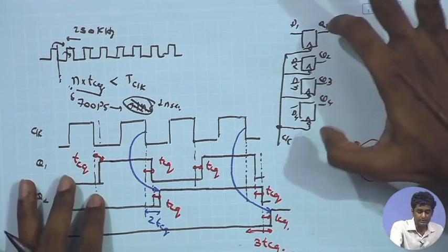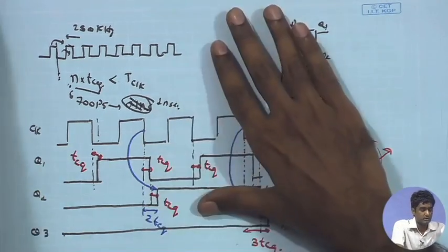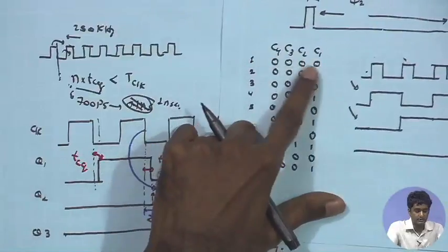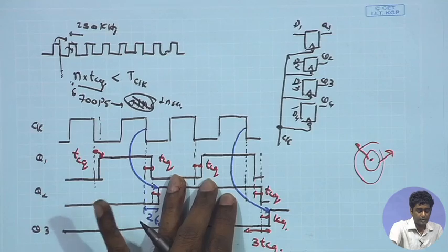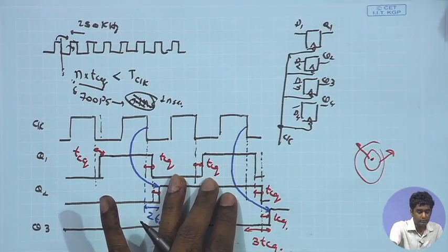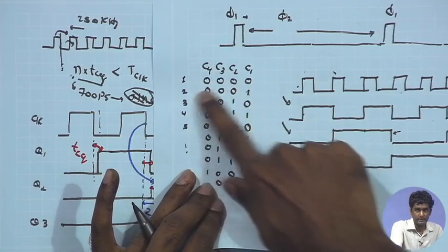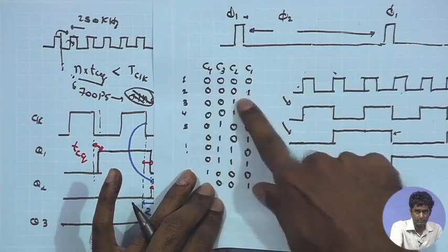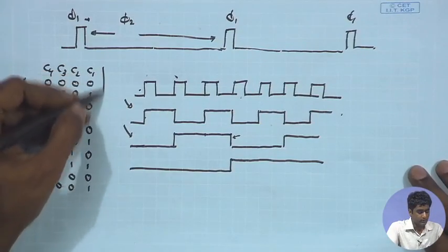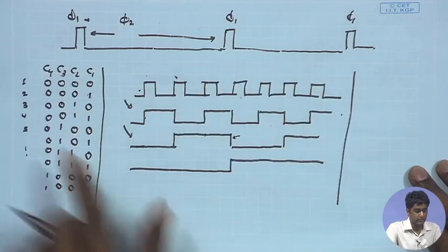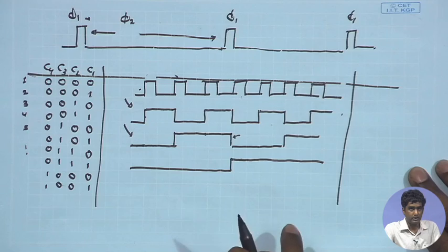Here I have to make sure that this Q1, Q2, Q3, Q4 follow the truth table that I want. So, just like the truth table that we discussed, the transition in Q1, Q2, Q3, Q4 should follow this truth table, and for that I need to figure out that if the present state of Q1, Q2, Q3, Q4 is a certain bit configuration, what is going to be the next state. So, for that I need to construct an output state for a given truth table. So, avoiding the repetition, I am just using this truth table already drawn.